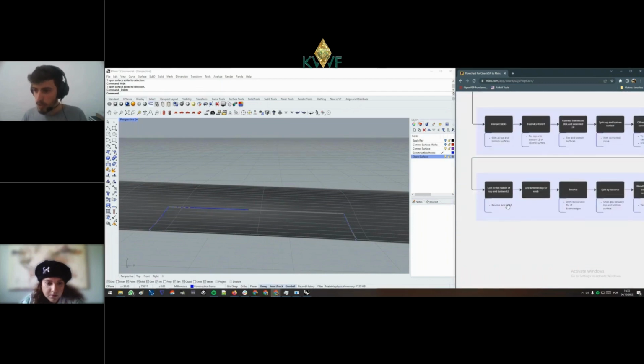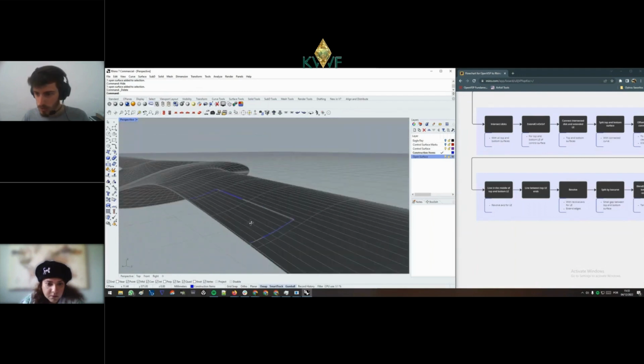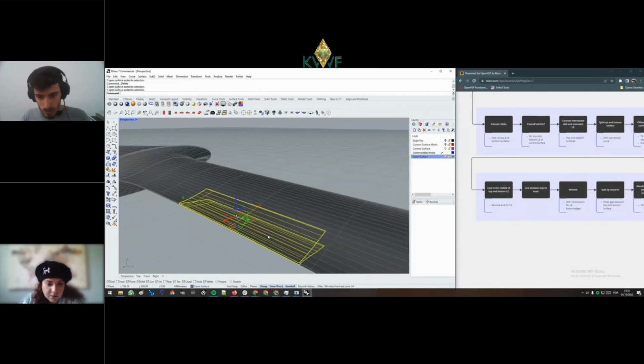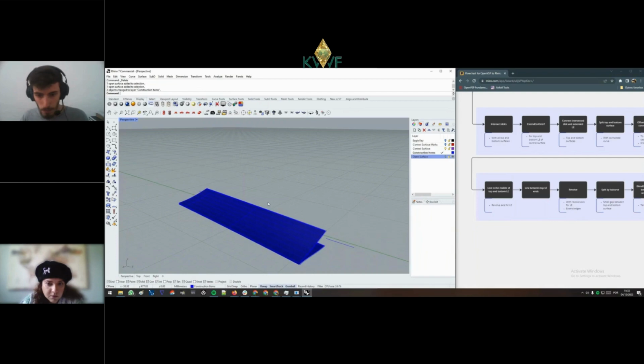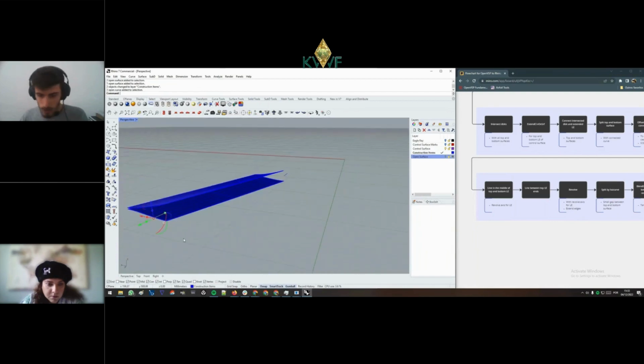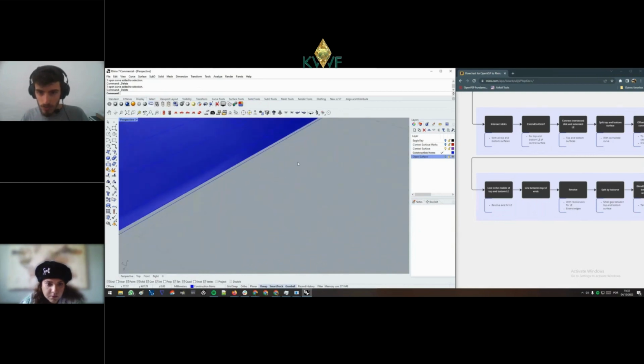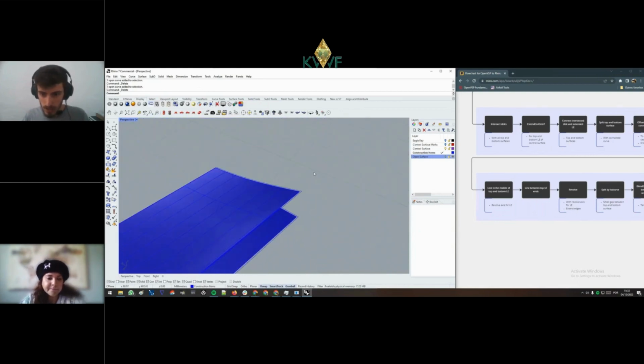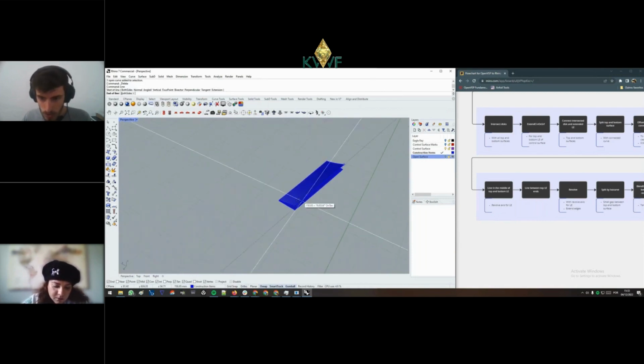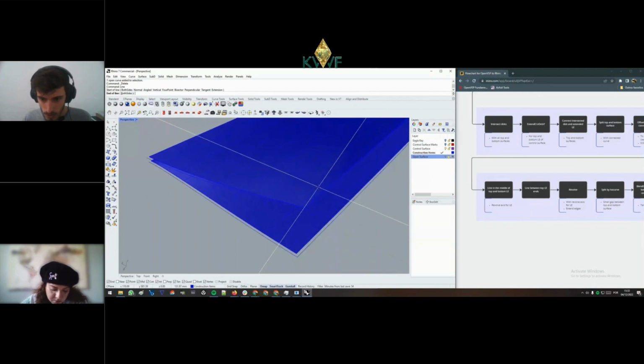So now we can move to the revolve for the leading edge of the control surface. Now I'll just change these two surfaces for this layer to be easier. And now is the actual step we will do the leading edge. So I'll create some lines from the top and bottom tips of the leading edge of the control surface.